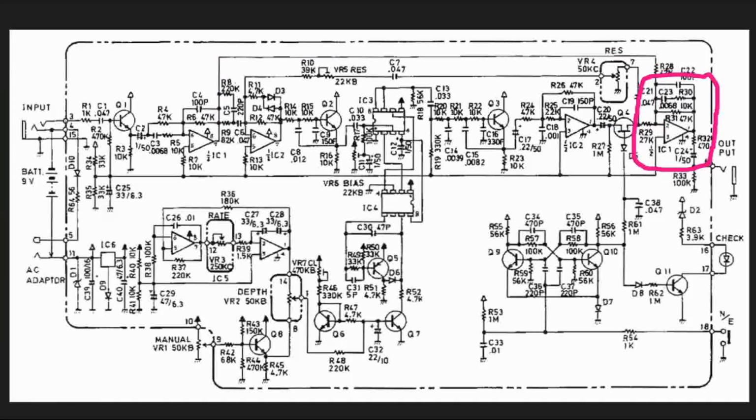So remember, earlier in the circuit, we had a pre-emphasis filter right here that is boosting the high frequency noise or the high frequency signal to overpower the high frequency noise inherent in the BBD so that we get better signal to noise ratio. But we don't want our signal to have all of that extra high end in there.